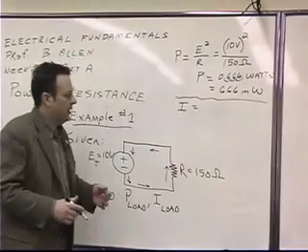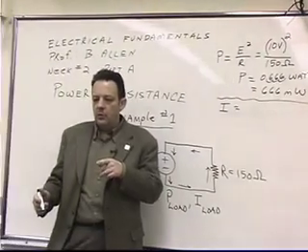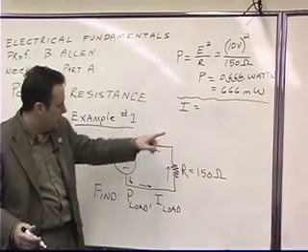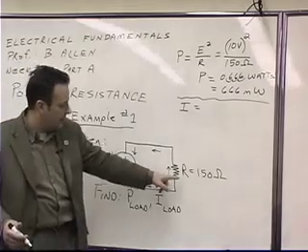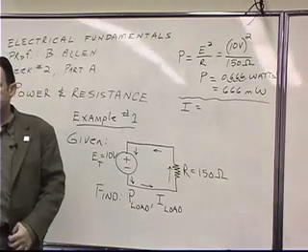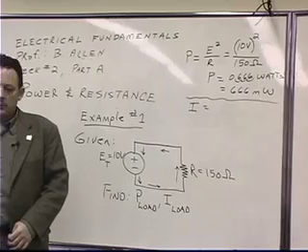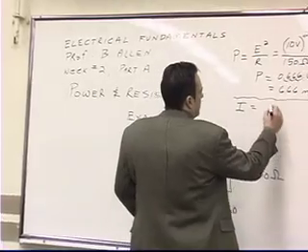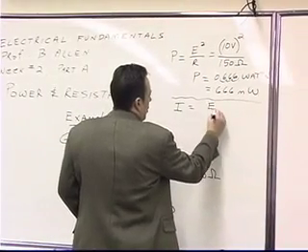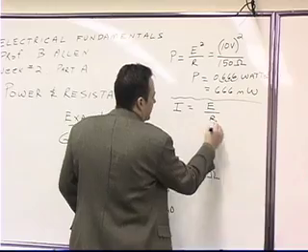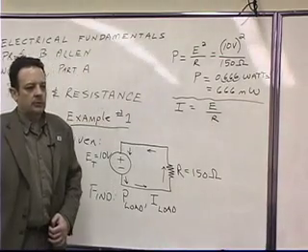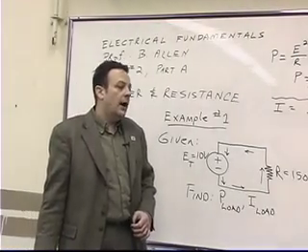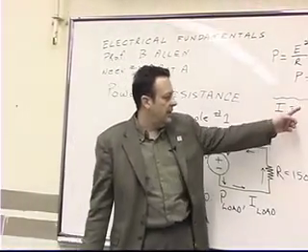Okay, so again, if you look at your Ohm's law formula wheel, and you want to find out what current is equal to in terms of volts and resistance, what is it? What's the formula? Current equals what? Current equals P over E. Current equals volts over resistance. But we have P and E, or I guess we can do that. You could also use P, but let me tell you why you would be better off using E and R.